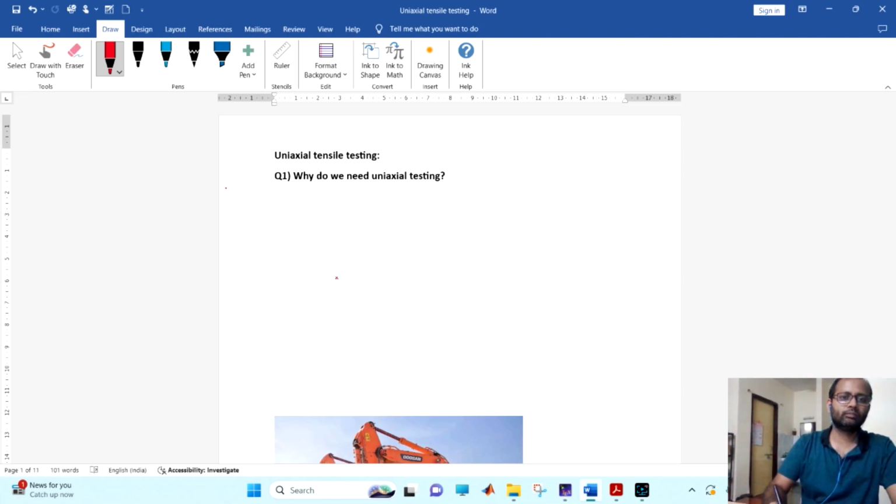Myself Deepak Maurya. In this video lecture, I am going to explain the uniaxial tensile test. The first question arises: why do we need uniaxial testing? Whenever we are going to design any machine component or machine, we should know where it is going to fail, at which position it is actually going to fail, and at what maximum load it can sustain. For that we need uniaxial testing for a particular material.